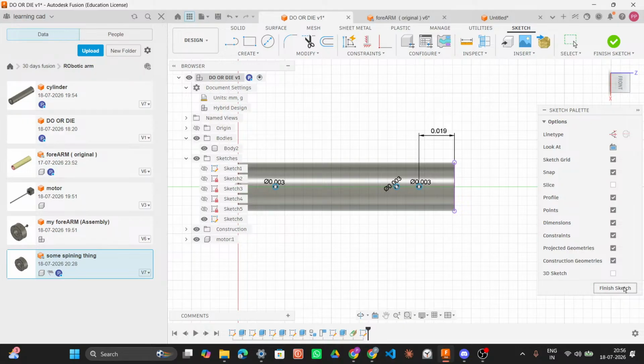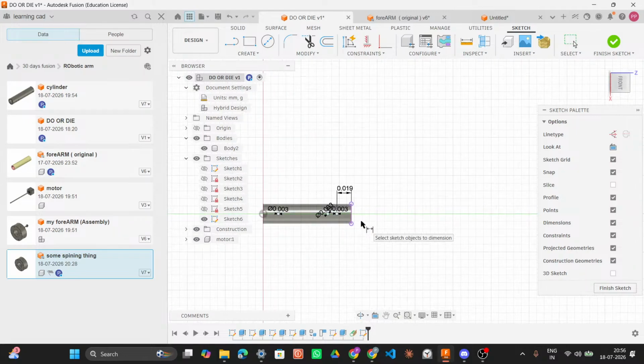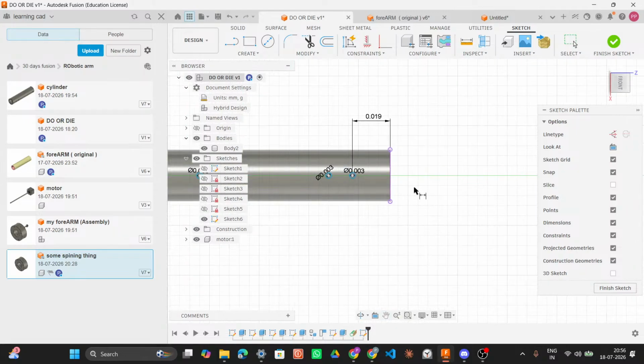I'm just going to submit this part at this scale and we'll figure it out when we assemble. Yeah, at least so that you could zoom in, because if the holes are currently a 0.003 diameter, I wouldn't be surprised if they were supposed to be a 3 millimeter diameter. So you could probably scale the whole thing by 100, and then that would at least let you zoom in and work with it easier in the meantime.